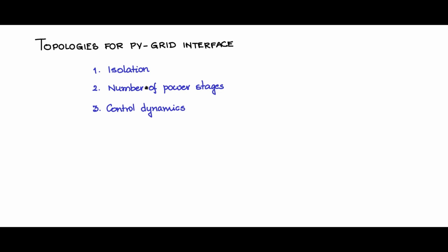So one by one, let me introduce the different types of PV grid interface circuits, and let us spend some time discussing them. Let me take up the following topology, where we have the PV module connected to a DC-DC converter, and the DC-DC converter output has a capacitance.